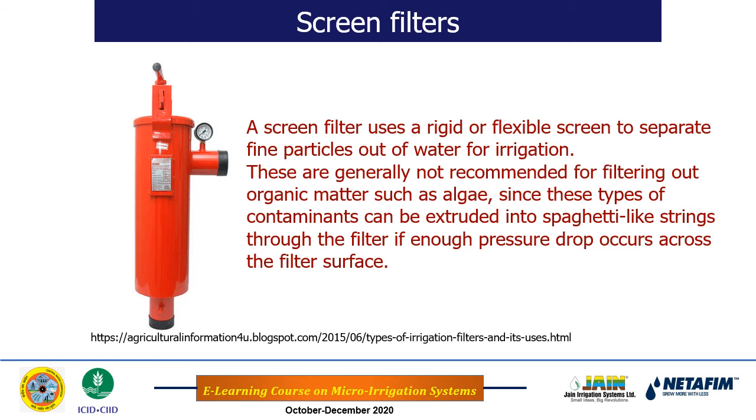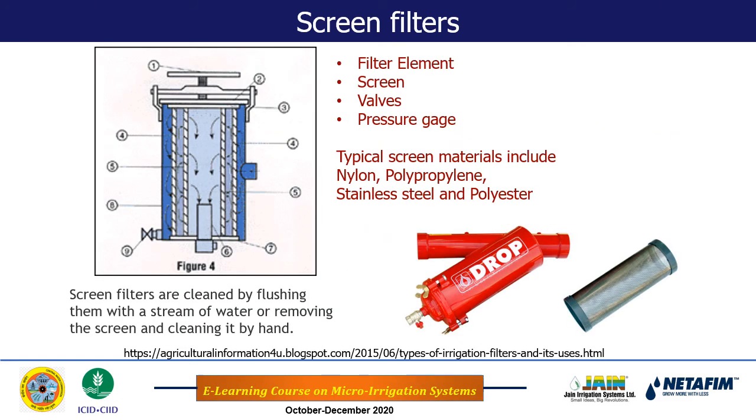We have experienced that if we use algae water or water with organic impurities, the screen filter is blocked even in one day itself, so it needs to be taken care of.